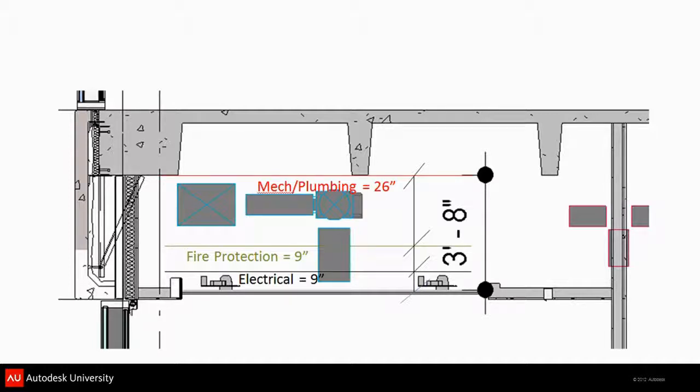It's a quick guideline. It's a 2D sketch. Sometimes we'll do this on a whiteboard. We will project the Revit model, and we'll ask some of the seasoned members of the team, let's walk around. Where do you think are going to be the choke points on this job? Then we cut a section there, and we just take markers, and we draw up, okay, you're here, you're here, you're here, and we take a picture of it. These are very simple non-BIM things that can save many BIM hours.